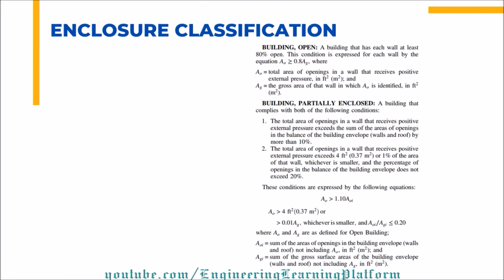The next is open building. If each wall of the building has more than 80% of opening, then your building will be called an open building. The third is partially enclosed building. Now, to be partially enclosed, it needs to satisfy both these conditions, that is 1 and 2.